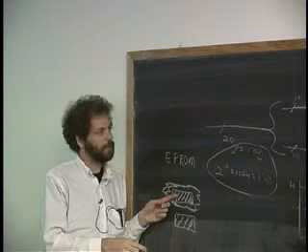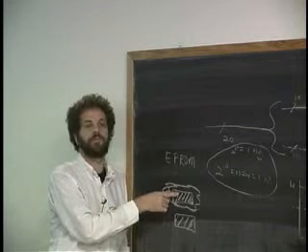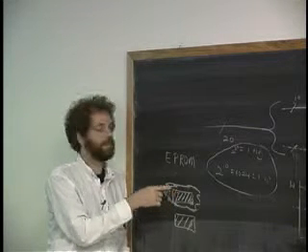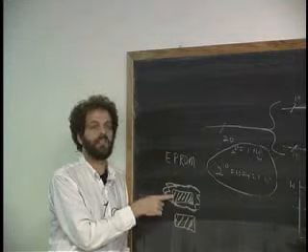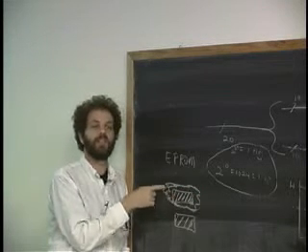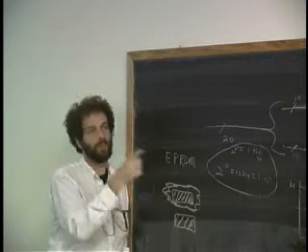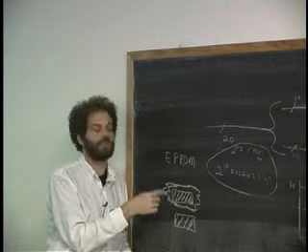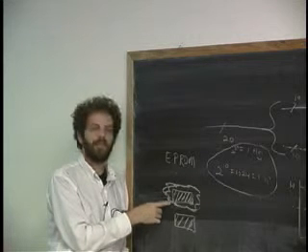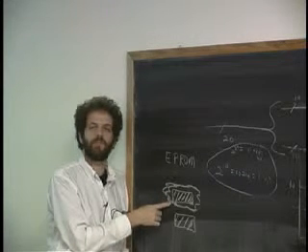The capacitor is like this, except that there's no switch hooked up to here. Okay, and because there's no switch, the switch can't leak. And because it doesn't leak, you don't need to refresh it, and the charge lasts for 20 years, and even more in the case of that thing, at least 20 years. If you get it real hot, it lasts for less. So how do you store energy in here to begin with?